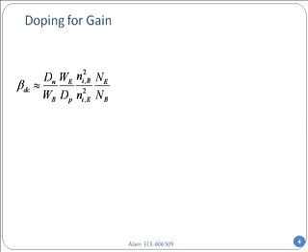So I have already explained this particular expression for current gain. You remember beta is the common emitter current gain, that if you put a certain amount of base current, how many times does it get amplified before it gets to the collector, right? Base current is small, and typically these numbers are on the order of 100 to 1000. You don't want it very high because then the transistor will become unstable in the circuit context.